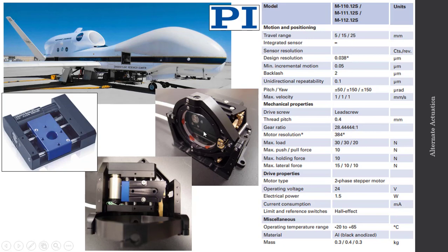So this piece of glass here is a mirror for ultraviolet wavelengths. And this mirror rotates about 2 axes. We have a vertical axis and a horizontal axis. To achieve that rotation, the assembly has 2 linear translation stages attached to 2 flexures, and in each stage from Physik Instrumente is a linear actuation assembly comprised of a stage, a lead screw, and a stepper motor.